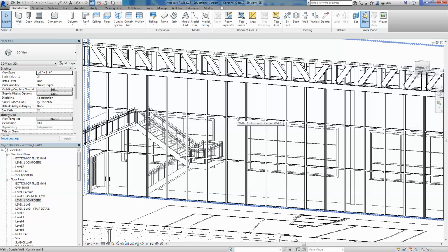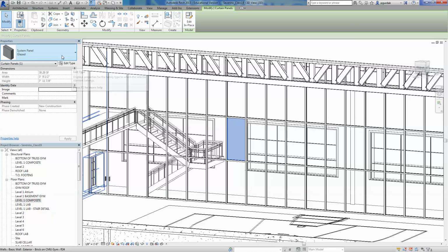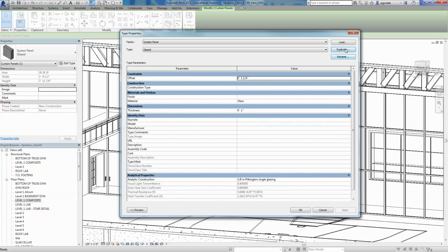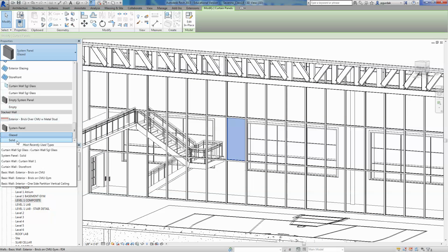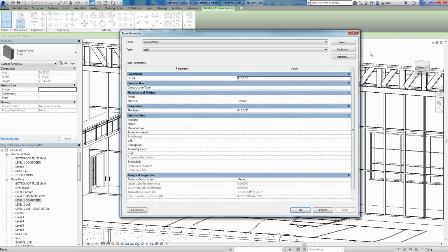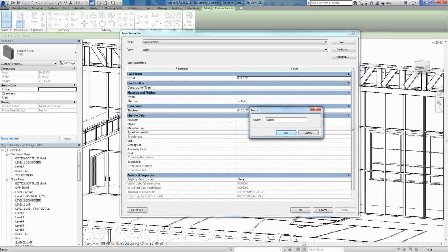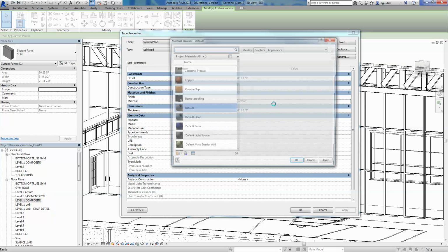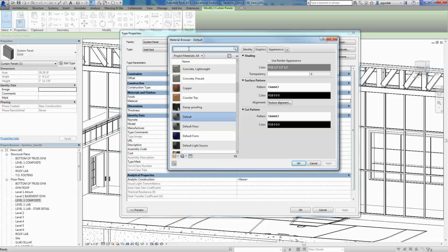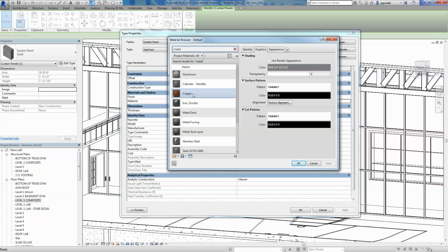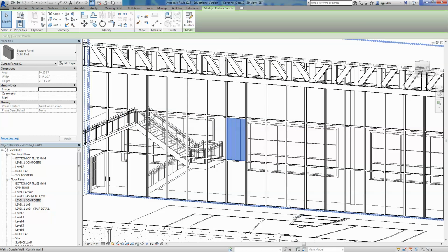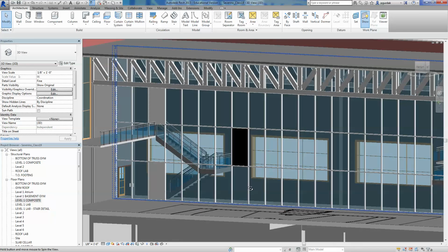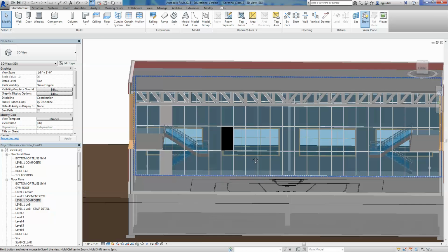You could make a design of different panels, and you could actually duplicate each of the panels. You can say glazed or solid. Wait, let me cancel that one and make it solid panel. I'm going to edit and duplicate. You can make it solid red color and change the material for that panel. And before we had this pitch about metal, so you can make one metal and copper, for example. Say okay, and it even has the pattern. If you go to the shaded mode, you should be able to see that difference. Good.